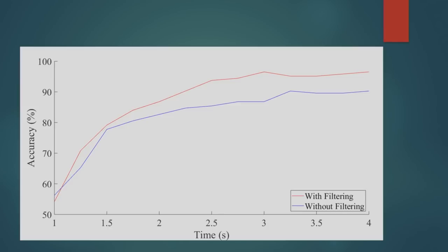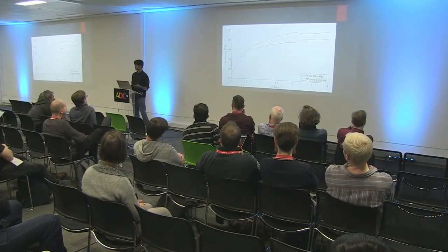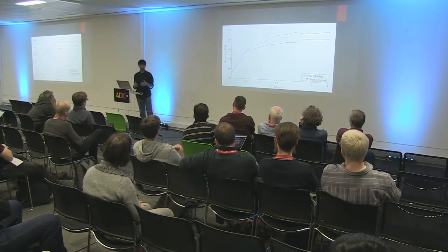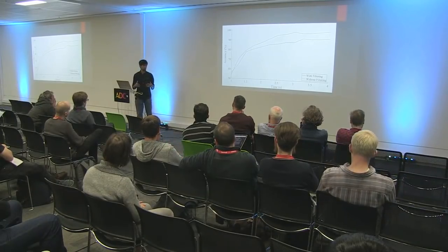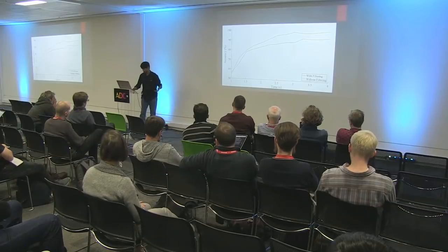In order to implement the filtering, FIR filters wouldn't be a practical solution, as obtaining a good enough frequency resolution would require high computational complexity. On the other hand, while implementing IIR filters, we would end up having nonlinear phase and phase distortion. Because of that, zero phase filtering was implemented, where you filter the signal forwards and you also filter the signal backwards. That way you end up having zero phase distortion. So zero phase filtering was implemented in this project for filtering EEG data.